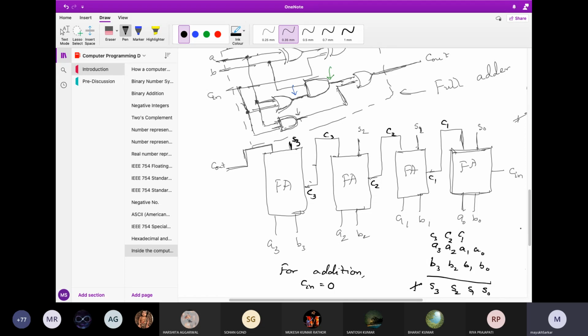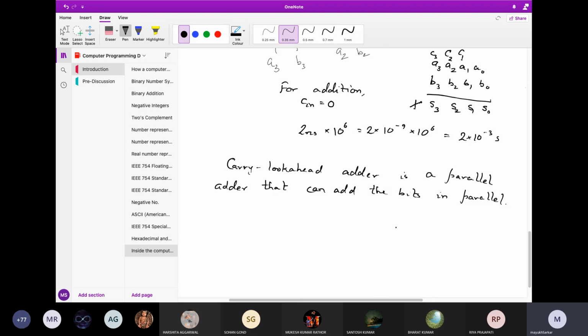And then suppose you have a 4-bit adder like this. I'll also show you one general convention. A and B are getting as input, each with 4-bit lines, 4 wires going through this. This is a carry in. The carry out from here is passed through another 4-bit adder.